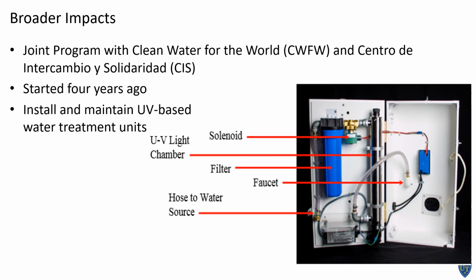In order to treat the water, what they have developed is the unit you see here. It's a UV light-based system that inactivates bacteria and viruses. Upon exposure to UV light, DNA can fuse. There's a chemical reaction that can occur between two base pairs. This covalent bonding of the DNA prevents it from separating and allowing the microorganisms to reproduce. Although the organisms are not killed, they're not able to reproduce if they're ingested.